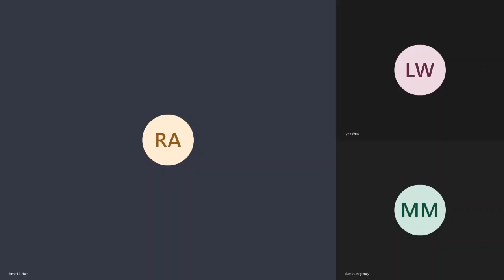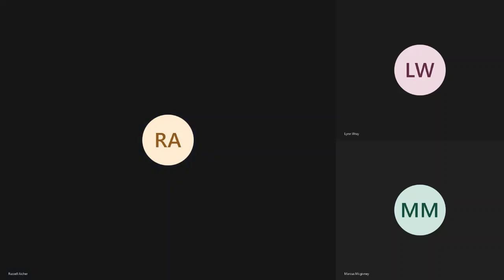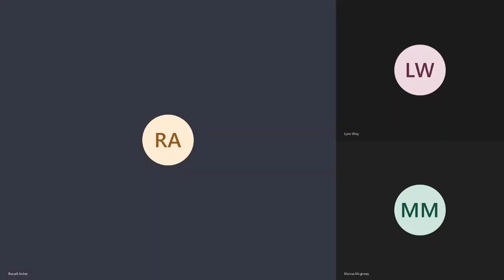The geodatabase format is going to depend on the user. Because you can actually, and we'll do this next week, create your feature class, create topology, and say you don't allow any overlaps. Lines that are within a meter should merge to each other. There's like a list of things that you can set up as far as rules. They can be useful, they can trash your data.